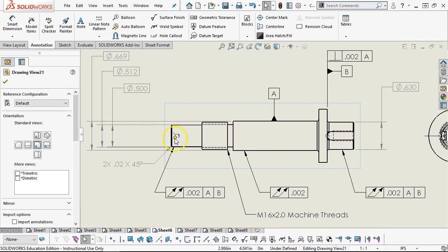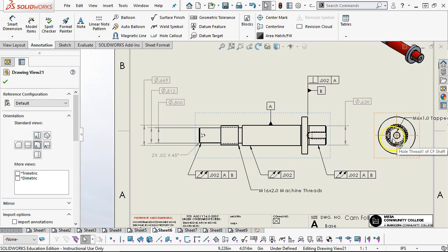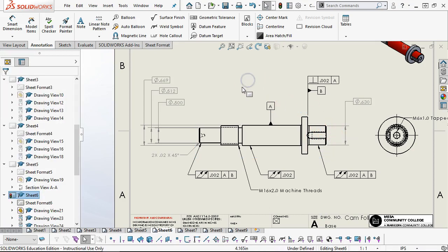And then I mentioned that we can put in either a reference or a notation that says the center drill is optional if it helps with manufacturing. Basically, because the other end ends up with the drill and tapped, they could put the center drill in there for the manufacturing process, drill the hole afterwards, and you would never know it was there. So that being the case, then